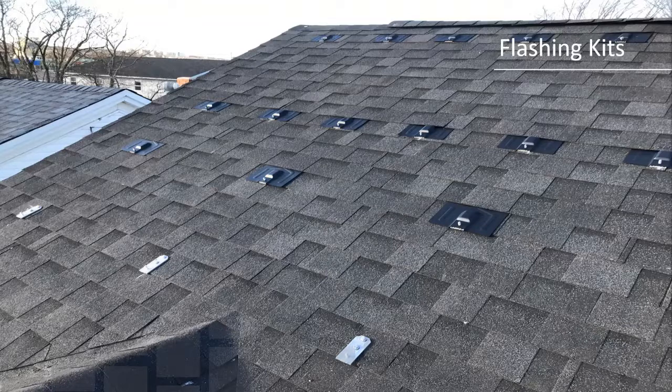Next, they mount the stanchions or the brackets with lag bolts to the actual roof. And you can see here, here's your threaded stanchion, here's your two lag bolts. These are gasketed. These go directly into the rafters. Spacing is typically 48 inches. Older homes may require what you see up here, 24-inch spacing, just to balance that weight out on top of the rafters or truss. Once this is in, these legs are gasketed, as I mentioned.